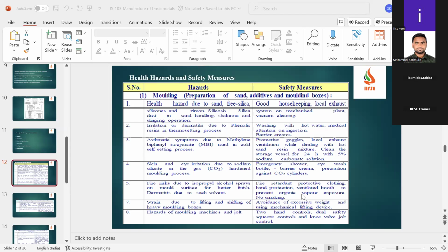And also, all these body wash showers and eye wash showers have to be checked once a day. They are installed for emergency purposes, but we have to cross check. We can give this responsibility to the safety department or the concerned department for whom we have installed them. At least they should take responsibility to check, because sometimes there will be blockage. Sometimes if you are not using them for longer durations, dust particles may come out because it is under pressure. That has to be maintained.